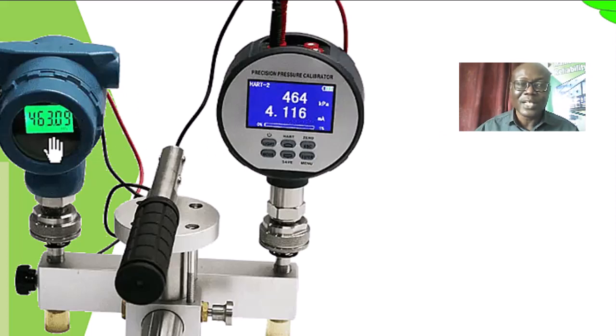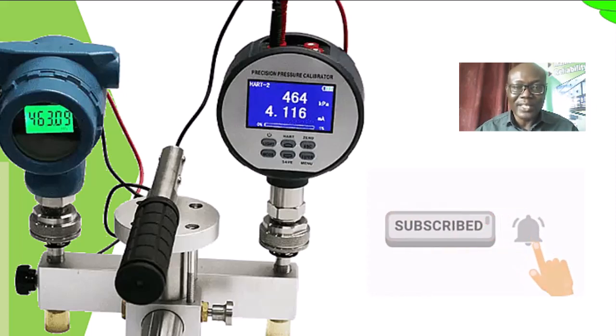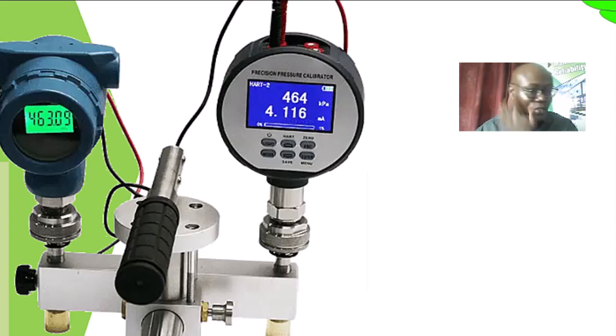Then the one that we are looking at, that is the instrument that we want to calibrate, is giving us 463.09 kilopascal. So we have a little difference, about 1 or less than 1. So if it is within the tolerable limit for this particular meter and for our own process, if 1 kilopascal difference will not affect our process, then we can continue using the meter.